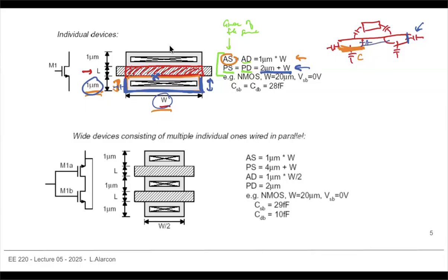That's how we write out our SPICE model. When we instantiate transistors, we actually put it there. Now, the problem is, it depends on your simulator. Some SPICE versions, if you don't put the source and drain, will just put in 0.